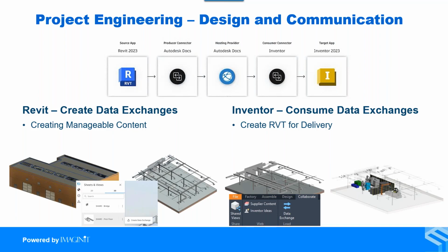Now, in the Revit side, you can see exactly what Brian did there on the left-hand side. He said, I'm going to create just this area for Mark to focus on, right? So I don't need the skylights. I don't need the garage bay doors. My equipment should fit through there, so I'm not too concerned about it. And inside of Inventor, my job is to consume that, which I bring in through the data exchange tools in Inventor, and then do my work, and then create an RVT for delivery back to him to check against.